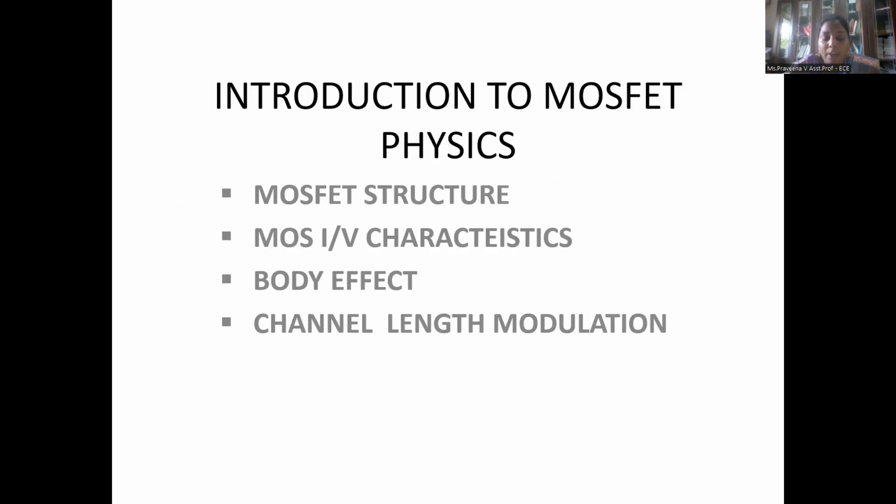GDS, I will remind you. The gate is insulated from the semiconductor channel by a thin oxide layer, right? By applying a voltage to the gate, a conductive channel is formed between source and drain. This allows the current to flow. MOSFETs are widely used in CMOS integrated circuits due to their low power consumption and high switching speeds.